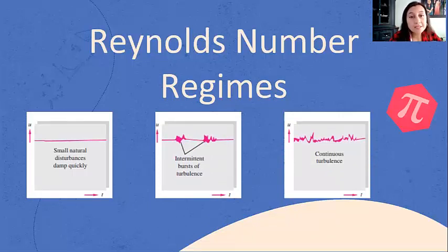The fluid ceases being smooth, steady, or laminar and becomes fluctuating and agitated, or turbulent. The changeover is called transition to turbulence. The transition depends on many effects, such as roughness or fluctuation in the inlet stream, but the primary parameter is the Reynolds number.